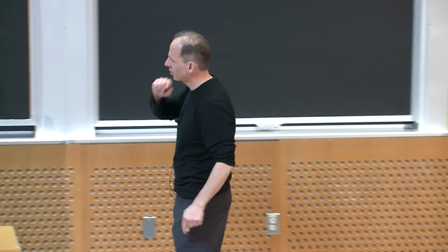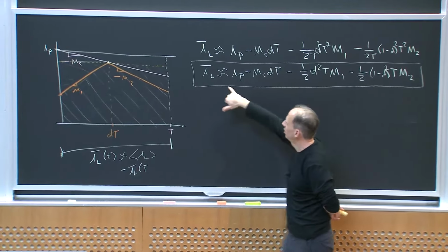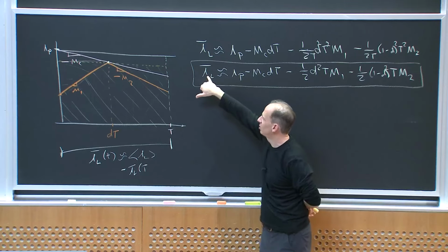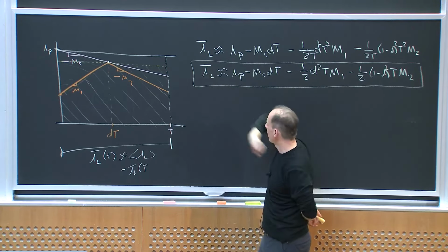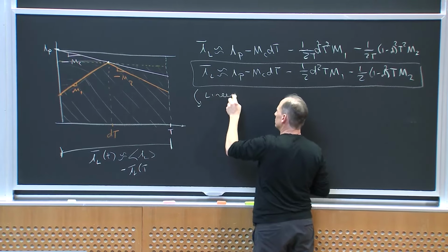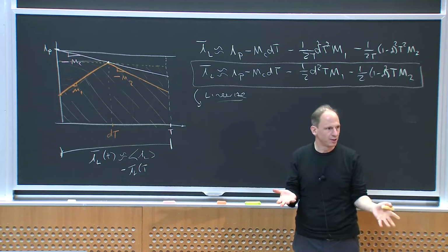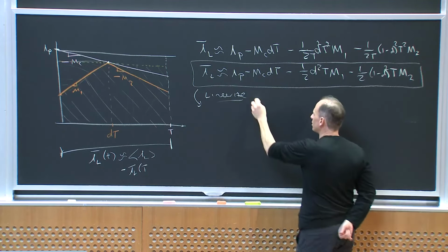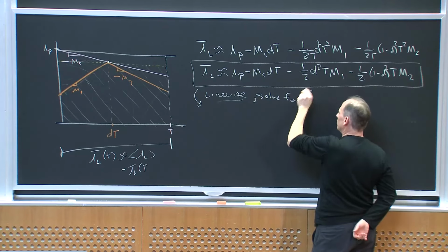So I've got a geometric approximation relating the duty ratio in the cycle, the peak current in the cycle, and the local average in the cycle. Let me linearize this because we're going to substitute into our linearized equations, and I'm going to solve for d tilde.